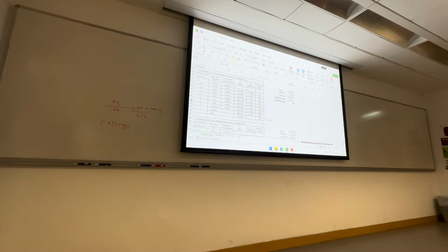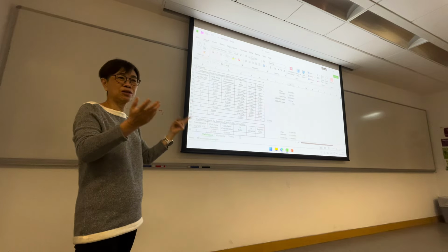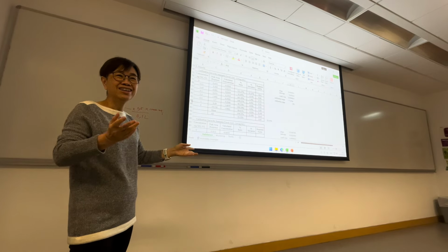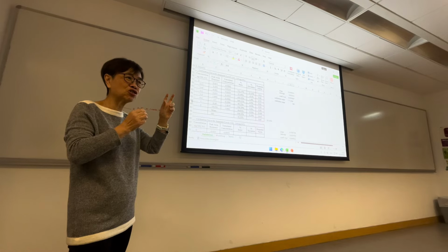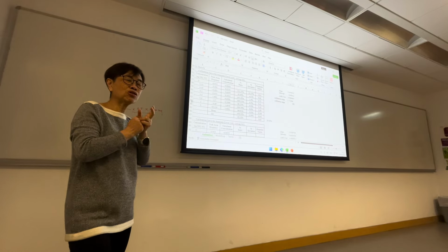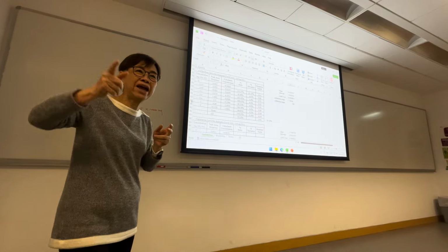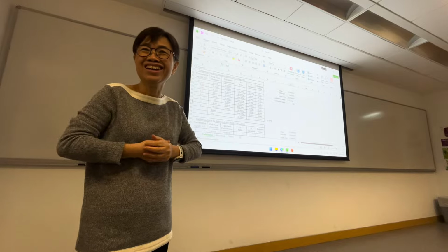The second is whether this is a linear plot, whether there is large deviation, or whether there is saturation. So maybe rejection of the lowest point, maybe rejection of the highest point, I don't know, okay? That is how to comment, and whether the calibration range is good enough. If I set a calibration curve from 0.01 to 10 ppm, can you say that this is a good estimation?